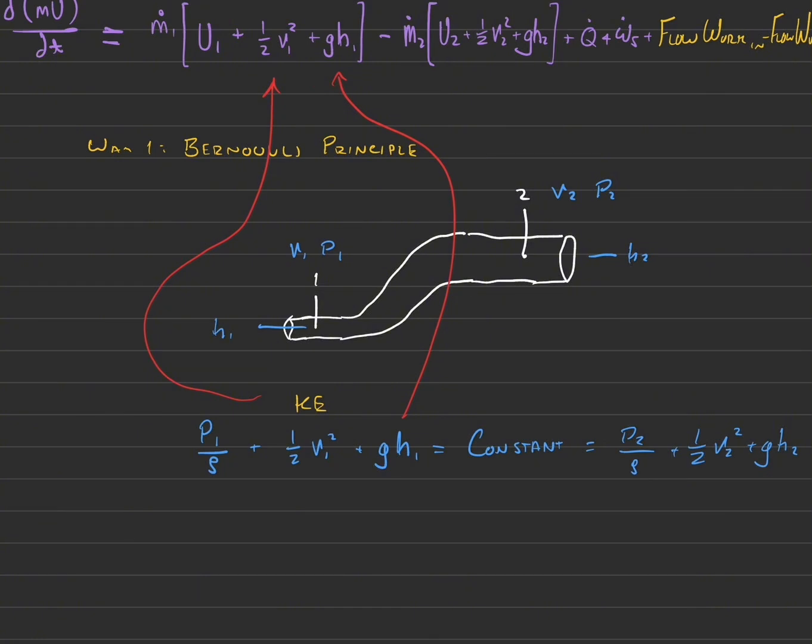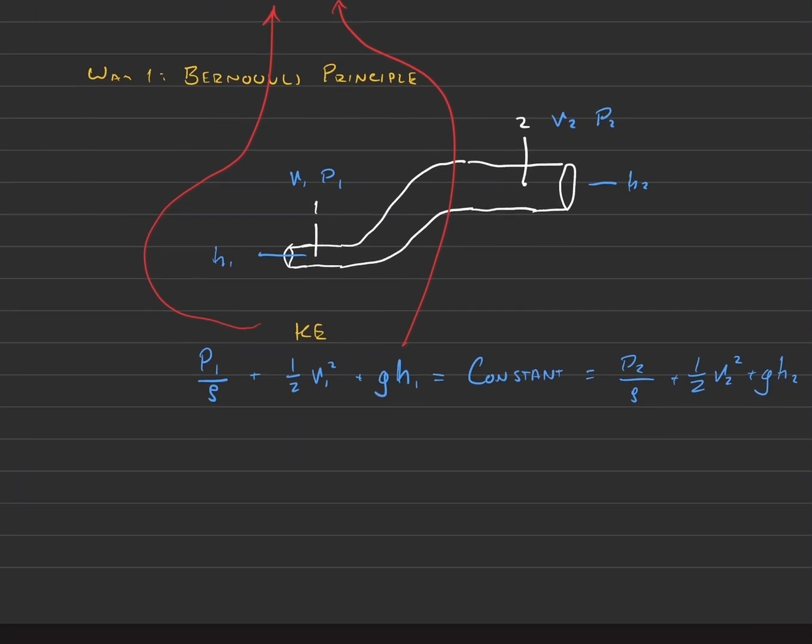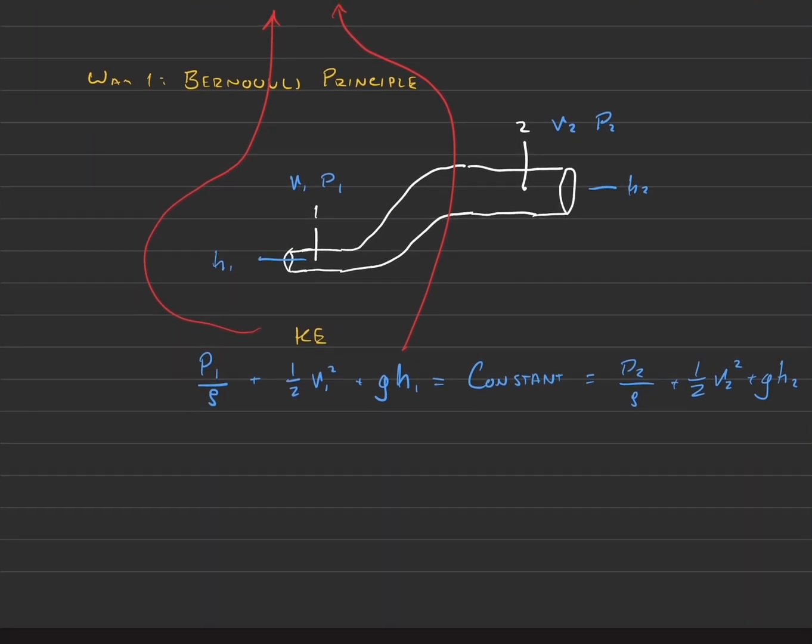But what even is the pressure divided by rho? Well, in terms of units or variables that we use in thermodynamics, we don't like to use rho very often. We prefer to use volume. And you might say, why would we use volume in this case? Well, rho is going to be in kilograms per cubic meter in SI units, which so happens to be the exact inverse of volume in units that we use in thermodynamics.